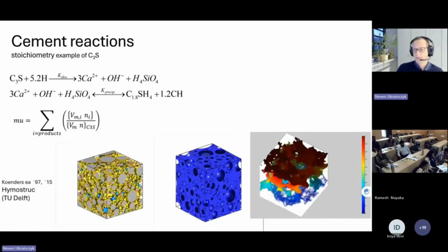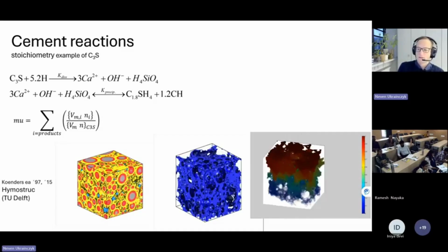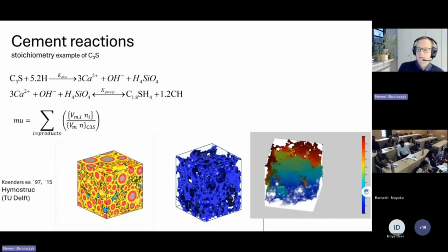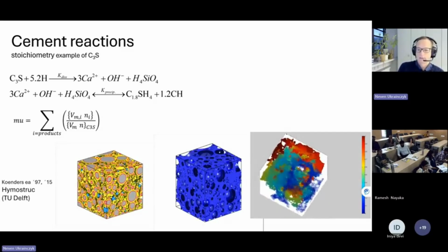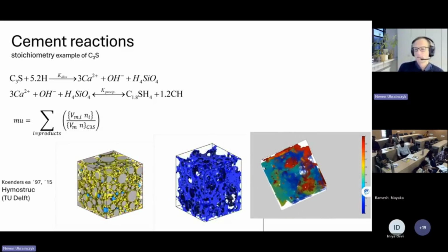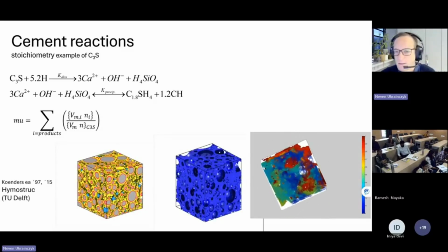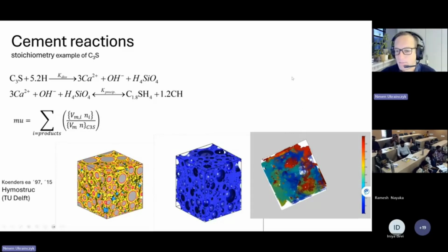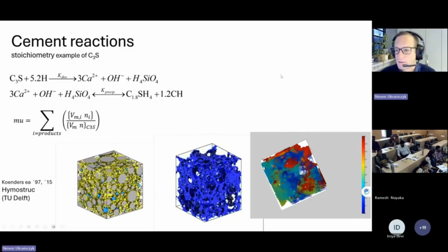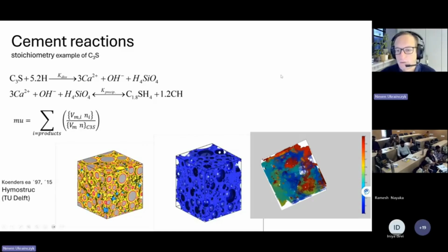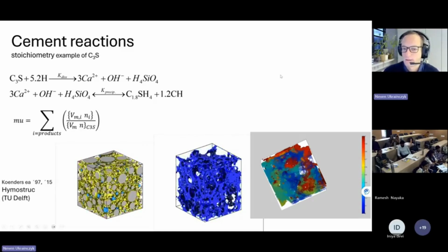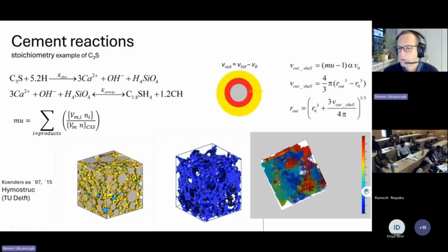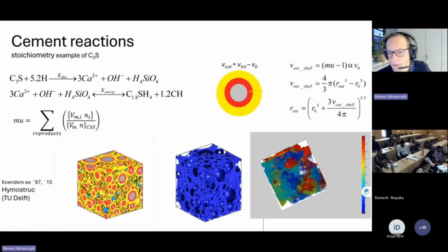And if you have slow reacting pozzolans, then this is always an ongoing reaction, so you also have a change in the microstructure properties. So the hydration is always connected with durability. Actually, we need to solve both together. I will talk about it more tomorrow, but now let's focus back on our volumes.